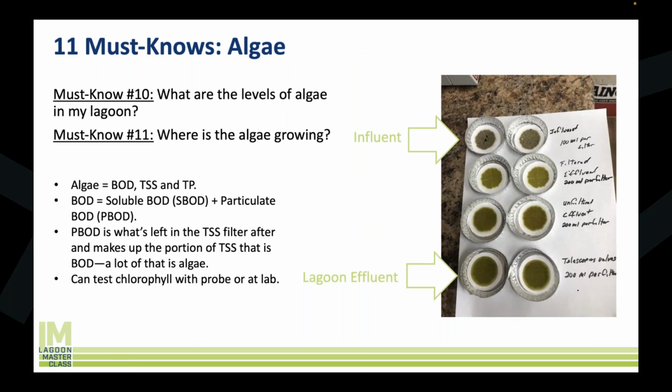I mean, that's pretty obvious. So at the effluent, this is kind of what we'd expect. You've got sort of gray and black, right? Gray is basically biological sludge solids. Good stuff, you can volatilize it, you can break it down. The black is usually old sludge or just different things that are probably harder to break down. Then as you move through the plant, you can see that it's green, right? So what does that tell you? Well, that tells you you've got algae in your plant, and the level of brightness and denseness tells you how dense that algae is.